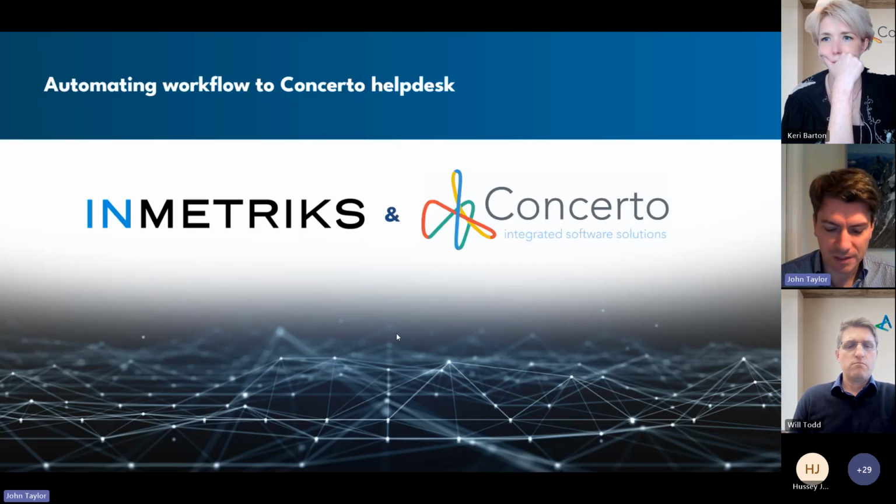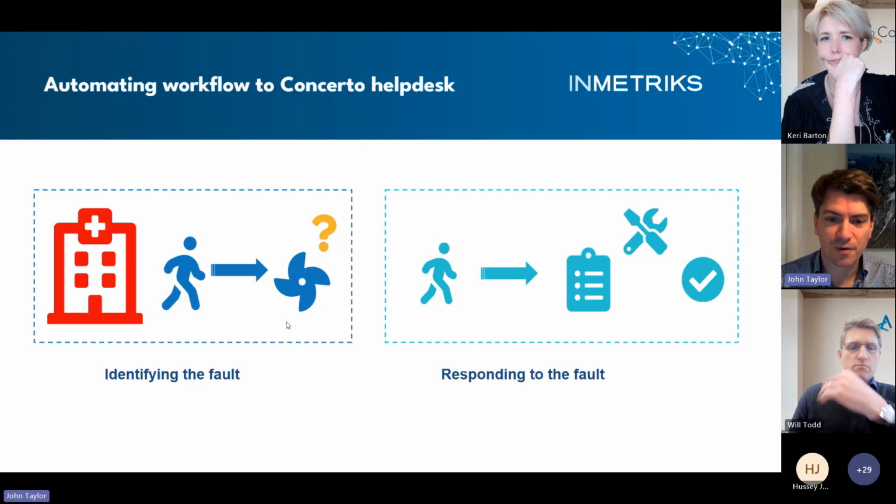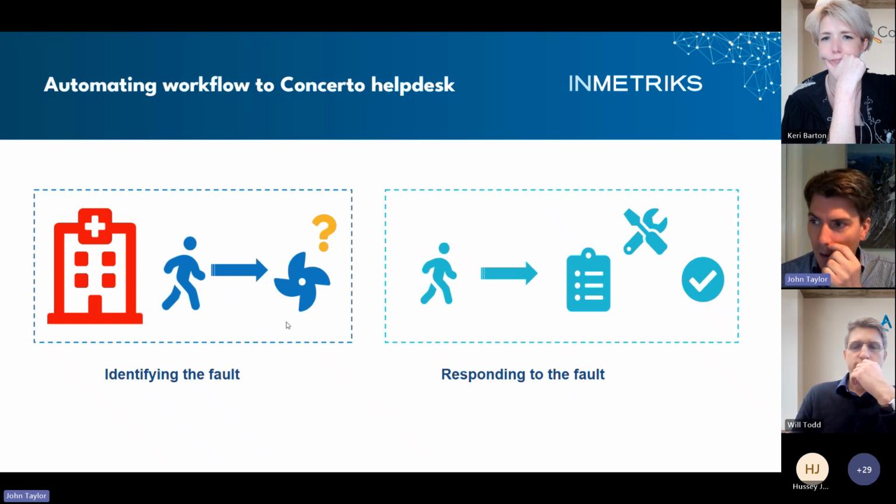Concerto is designed to make that workflow from problem to solution to implemented work, right? Concerto works that way, so we try to piggyback onto that. So a very simple workflow. You identify a fault. So we identify, like in this little diagram, maybe the fan has gone down, so you're not providing fresh air into a space, which could be pretty critical.